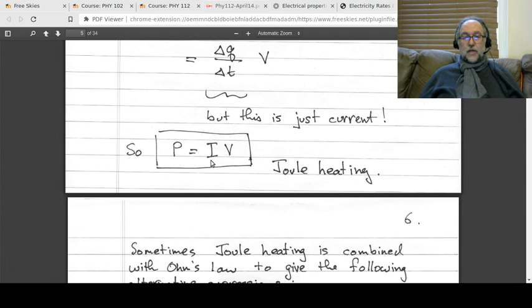So you got so much current traveling through that tungsten filament, and you got so much voltage across that there, because the tungsten filament has some resistance, so there's a voltage drop across the tungsten filament, and there's so much current going through there. You take the voltage, multiply it by the current, there's the power that is being dissipated as heat, okay? So there you go.